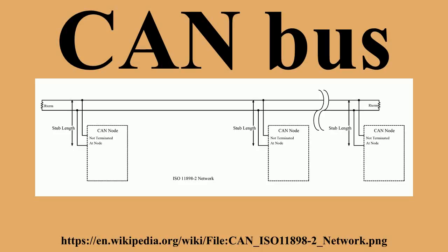This usually allows operating margin on the supply rail sufficient to allow interoperability across many node types. Typical values of supply voltage on such networks are 7 to 30 V. However, the lack of a formal standard means that system designers are responsible for supply rail compatibility.